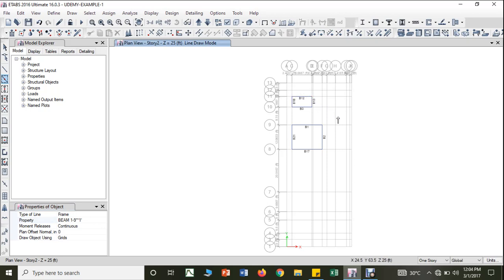If you have uneven connections of the beam, that time you can choose that option, or if you have very symmetric nature, then you can easily use this option, that is the quick draw option. So these are the two methods that you can use for drawing the beams.